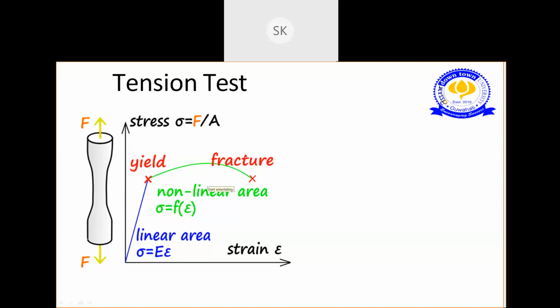Suppose I'm taking steel. Steel is a material, but suppose we have different geometry. For different geometry, there will be different cross sectional area and different change in length. So we don't take these; we generalize and take a stress strain curve for the material steel. Suppose you have a T section of steel and an I section of steel.